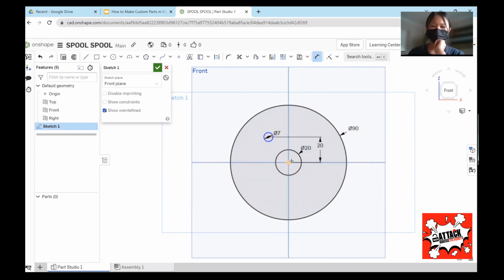And then you can dimension it again. I think you can also go up to the middle of the small circle and the middle of the middle circle, the origin, and that can also be changed to 15, so it'd be to the origin. I think this one needs to be changed. I think it's 15. Yeah, there you go. So it should be a circle and then a smaller circle, looks like half a face.